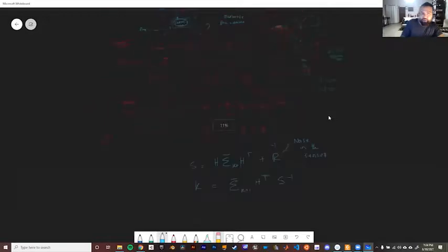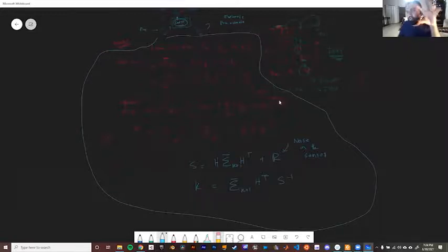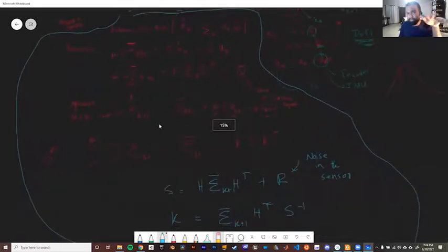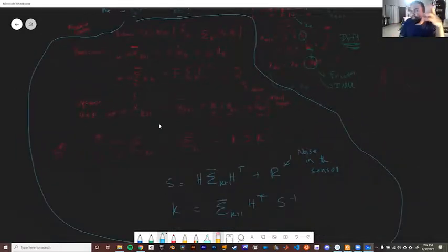I know it looks complicated and I think I might have lost a few of you, because I was just explaining the algorithm without an example. What you need to remember is it has two steps: the prediction step and the update step. The prediction step uses the motion model, the simple motion forward, while the update step uses the observation coming in. That's all you really need to understand for now, because I'm going to do a simple 1D example and all of this will be clearer and easier to understand.